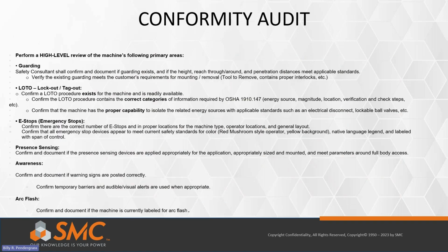What do we look for in a conformity audit? Guarding. Are the machines properly guarded? That's probably number one. Lockout, tagout. Is there a procedure in place? Are e-stops in the proper locations? Are there any presence sensing devices? If so, are they applied correctly?